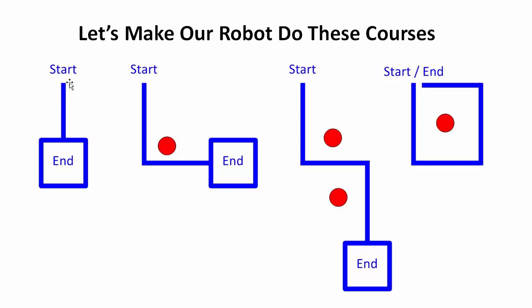But it's interesting getting started this way, because you start to see the impact of things like coasting, the momentum of the robot, and the surface that you're on. If you're on carpet versus a linoleum floor, it moves slower on carpet. You can also start to see the impact of the batteries wearing down over time. Maybe you have a program that works perfectly at the beginning of the day, and after 4 hours the robot just isn't quite making it to the destination, because the batteries are going down and the servo motors aren't getting enough juice.